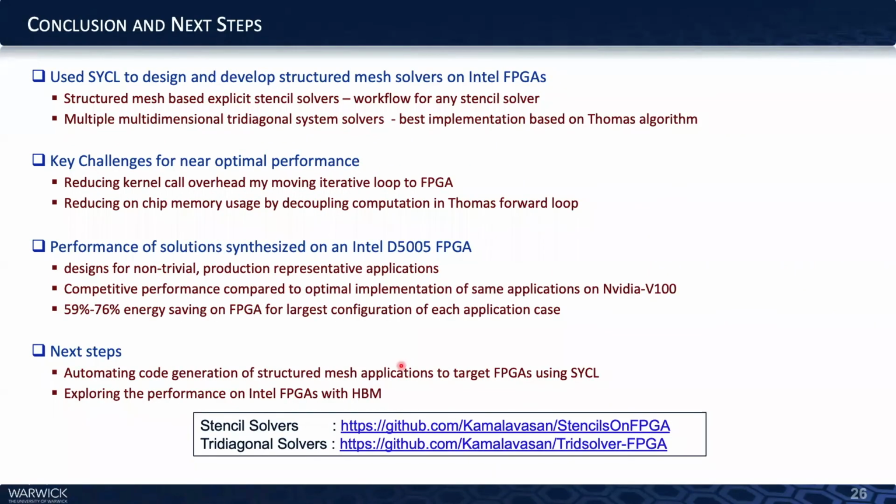We have used SYCL to design and develop structured mesh-based solvers on Intel FPGAs. This included a workflow for any stencil solvers and an efficient multidimensional tridiagonal system solver based on the Thomas solver. Key challenges to get near optimal performance on Intel FPGAs using SYCL are reducing kernel call overhead by moving the iterative loop to the FPGA and reducing on-chip memory usage by decoupling computation in the Thomas forward loop. We applied the workflow on two non-trivial production representative applications and implemented the design on the Intel D5005 FPGA.